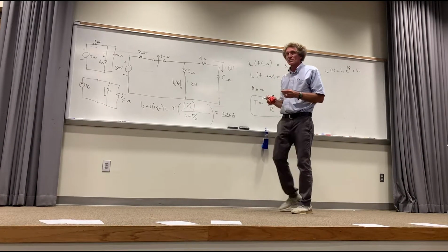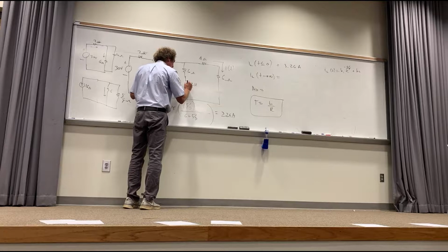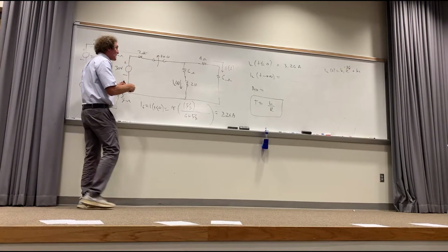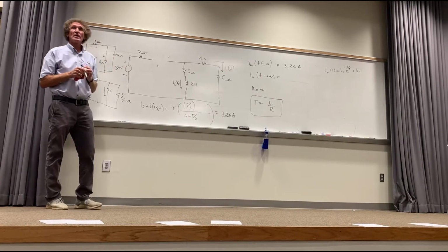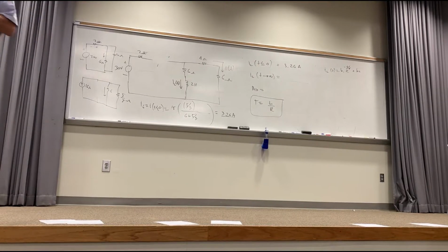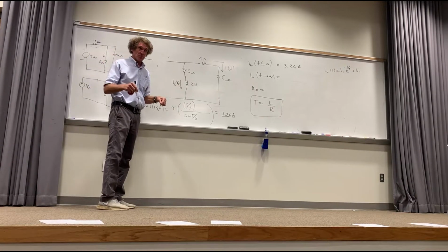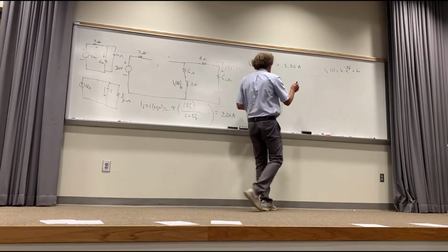Now, what is the current as t goes to infinity? I'm going to show you something on this one. I'm going to put the inductor back in so you can see it. It's 2 henries, right? Now, as for t greater than 0, or as t goes to infinity, this thing's open, isn't it, class? Now, what is the current going to be as t goes to infinity? Give me a reason, in your own words. How many see it's 0? Why is it 0? You're right. There's no source of energy to sustain it, right? There's no battery, no current source. If there is no source in the circuit for t greater than 0, everything decays to 0 if there's a closed path for current. And that means this will go to 0. So that means this is 0, which is nice.